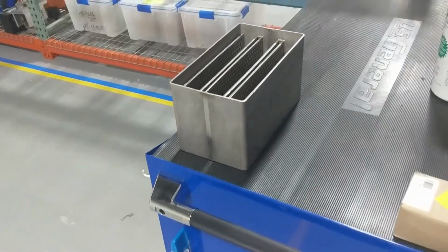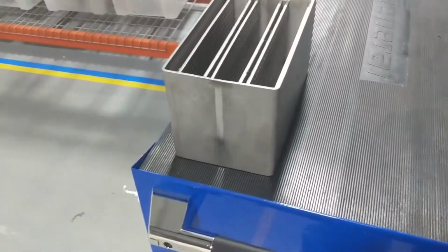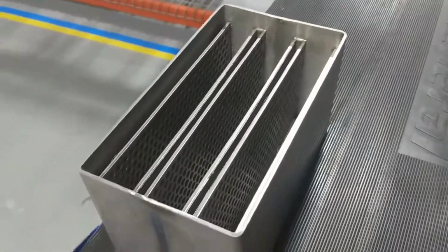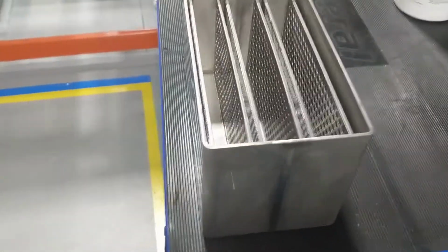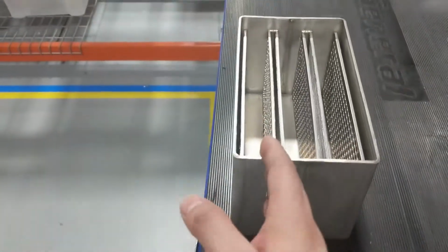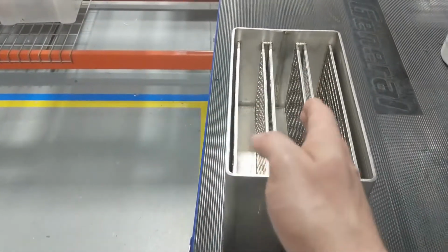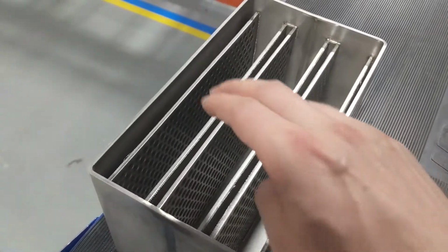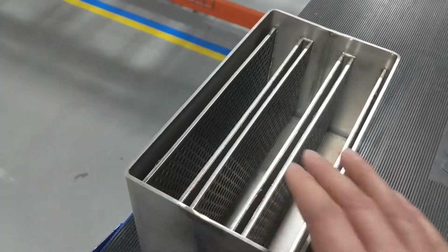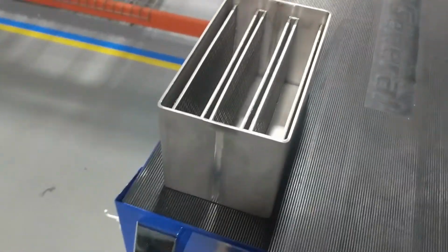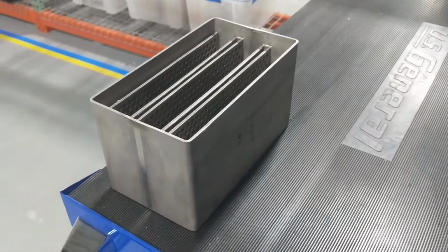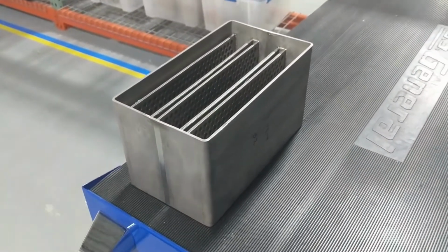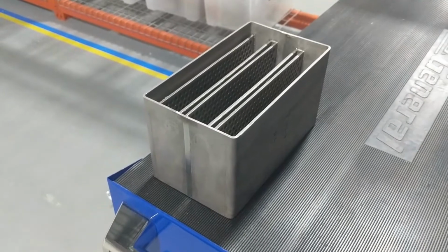I also want to share with you here one of the cell positive current collector assemblies that we've received from one of our vendors that we're really excited about. This is a cell assembly with 4 cathode bays into which we'll load a negative current cap that'll have 3 center plates here for the negative current collector. And the cell is assembled with the calcium and antimony loaded into each of these bays, filled with salt, and then welded shut. So we're really happy to see this. This is one of the cell components and assemblies that we're going to use as we scale over the 2021 timeframe.